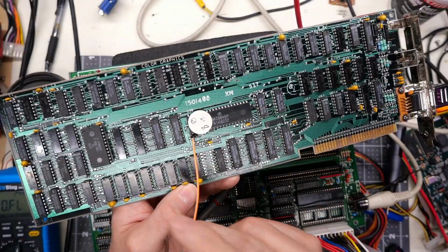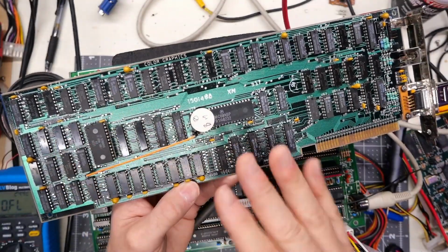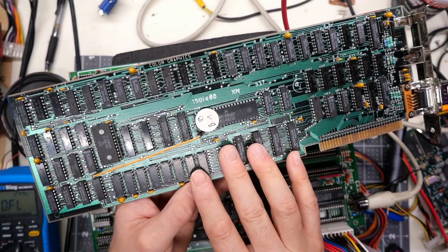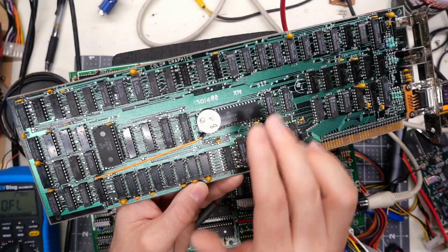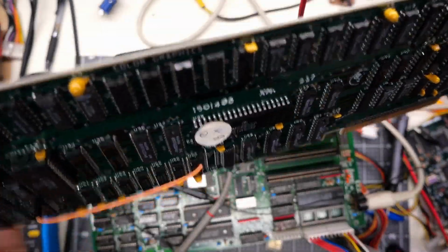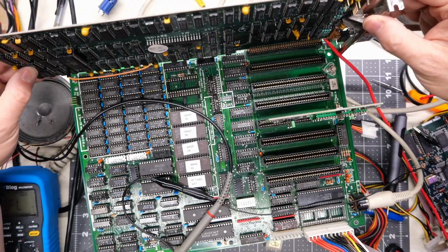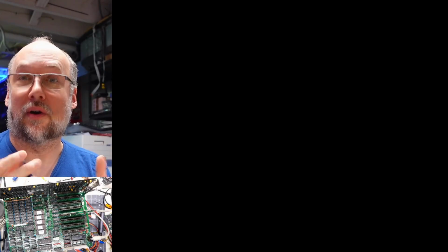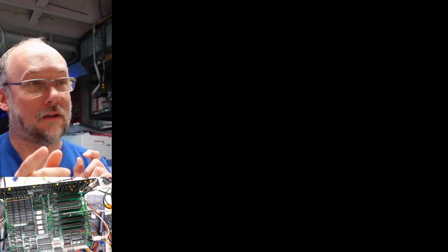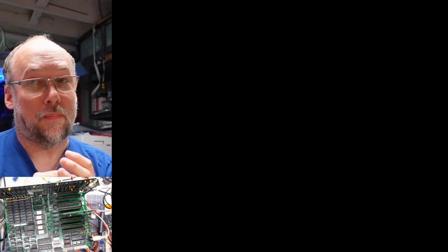So if we connect a wire from there to the flashing output, what I think that should do is anytime the system is displaying normal text, it should use the thin font. But when it's flashing, it should display the text in the double thick font, so like bold almost. Now, before I turn this on, my thought is that the screen should come up with a thin font, and then if we go into a program that displays flashing text, then that text should be flashing, but also be double wide. Now, if I cut a trace on this, we could disable the flashing, and that would change the attribute bit that changes flashing to not flashing text into double wide text or single wide text.